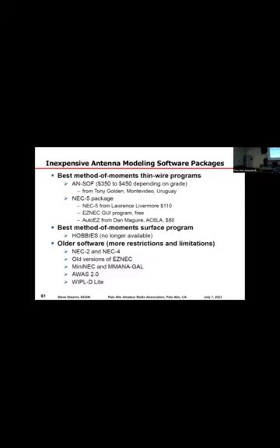However, the NEC2 program itself is the source of the inaccuracy, apart from the GUI. So that's the two issues: how good is the GUI, the graphical user interface, how easy is it to use, how easy is it to set up models, how much flexibility does it give you? And then there's the question of how accurate is the calculation engine? And the NEC2 calculation engine has a lot of tricks, or I should call them rules of thumb, you have to adhere to, or you get bad answers.